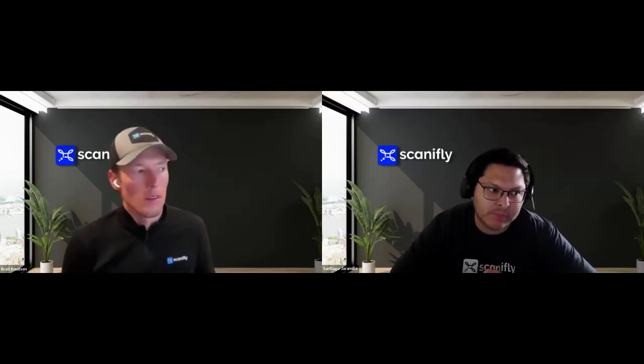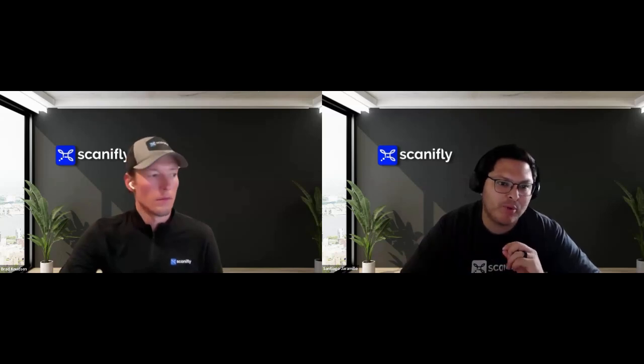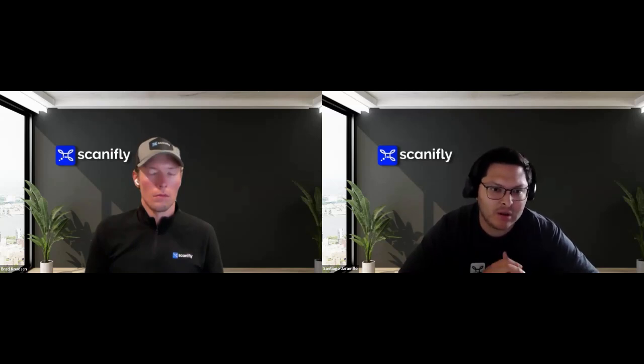Yeah, great question. We're actually drone agnostic. As long as your drone can geotag the photos, because the 3D model is created with a process called photogrammetry. So it's just stitching the images together and processing the metadata, which is the other important thing. Your drone needs to be able to capture GPS coordinates and altitude information, which most drones do nowadays. So those two requirements, high resolution camera and GPS coordinates, that's really what you need.